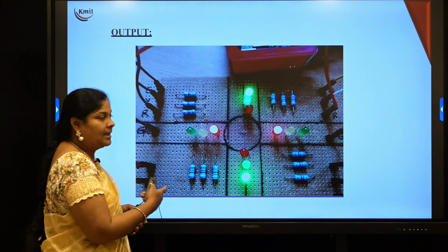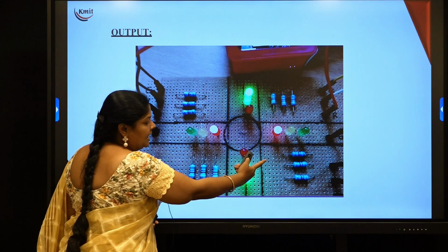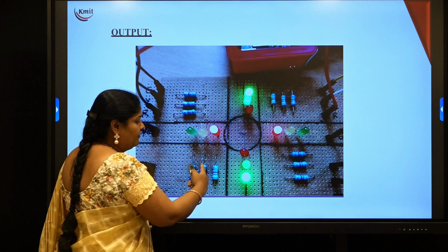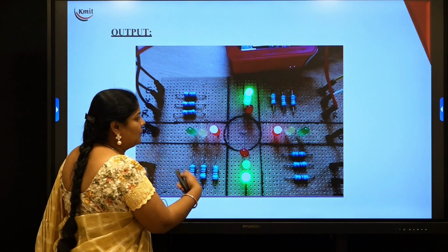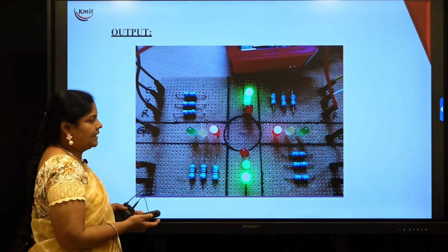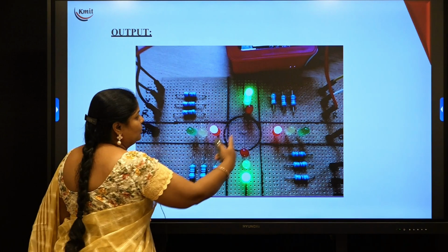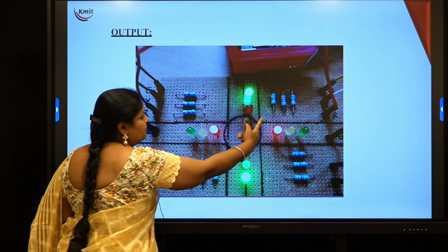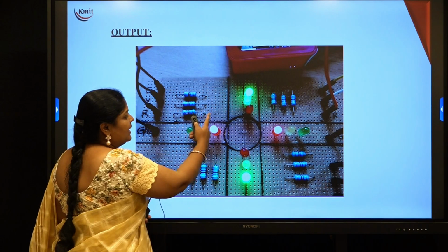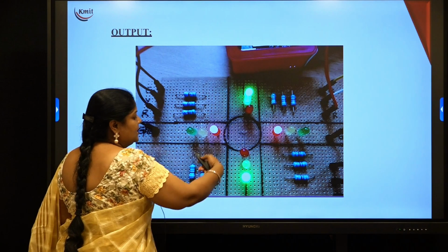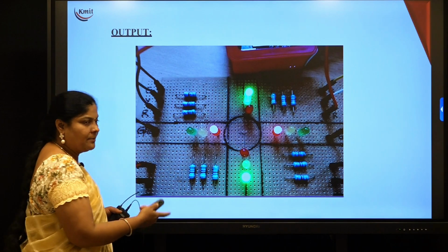Directly we can't change a green light to a red light. That is why we first change green to yellow, and then we can change the opposite lines from red to green. This will continue in a loop. After some time, we start from line 2 and line 4, the opposite pair. If we want to make these green, the opposite lines, 1 and 3, should be red, and 2 and 4 should be green. Like that, we are going to write the program in a loop.